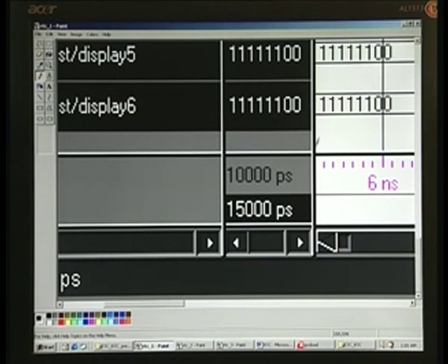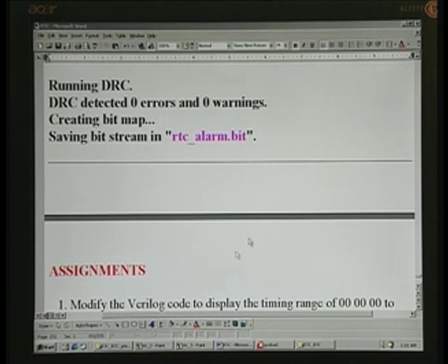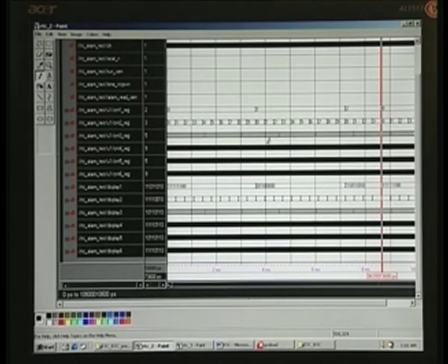So when you get to the fag end of this waveform, you will see differences reflecting counter 1 on display 1, counter 2 on display 2, and so on. And so we will go for the next waveform here. So here what you get is the entire cycle completed. So the real time clock has run right from 0 through 1 up to 2. This one is right up to 23. So we have 23, 59, 59, 23 hours, 59 minutes, 59 seconds, starting right from 0 here.